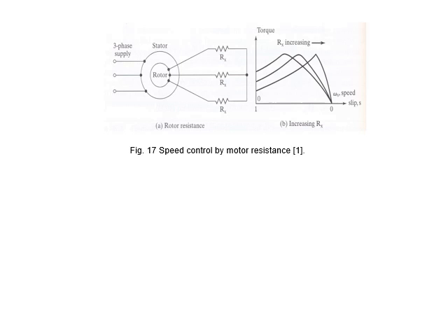Definitely, we have a squirrel cage and we have a wound rotor type. Squirrel cage, it's blocked. We cannot access the rotor, but in the wound rotor type, we can access it because there are brushes and slip rings, and we can then connect resistance, as you can see here. Three resistances. We connect them to the three terminals of the rotor. And then we control the value of these resistances, and we control the characteristics. See the characteristics here? It's moved to the right when we increase this resistance.